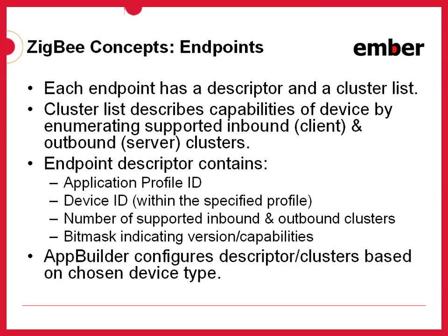So now you have a basic idea of how the ZigBee architecture is organized up in the application layer, with application profiles sitting on top of the stack, each application profile implemented on an endpoint as a single device type. So each endpoint implements one device from one profile, but you can have multiple endpoints on a single node. And that's how we get standard implementations of different devices running on a node.